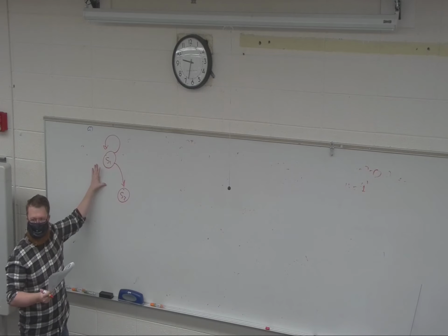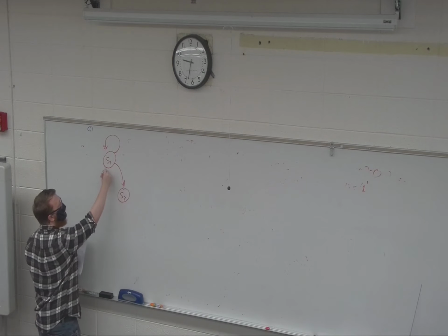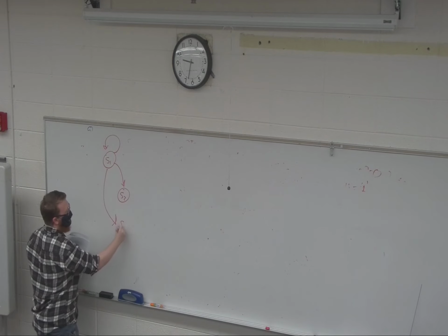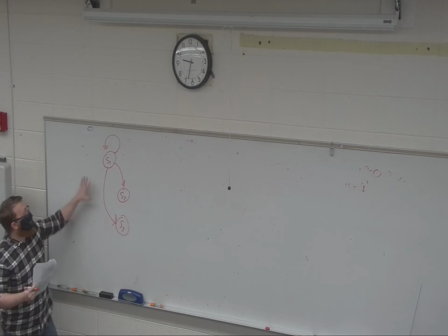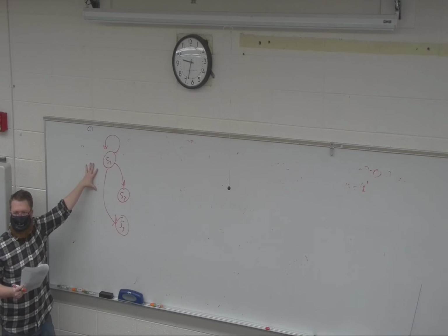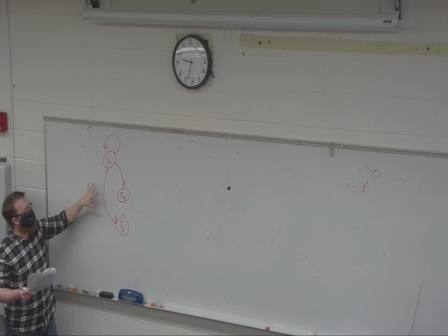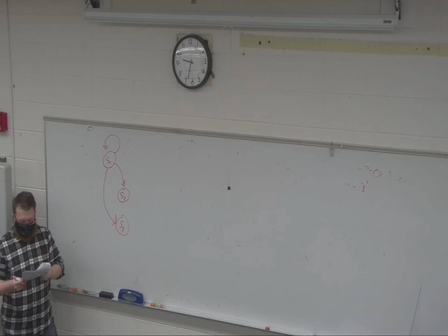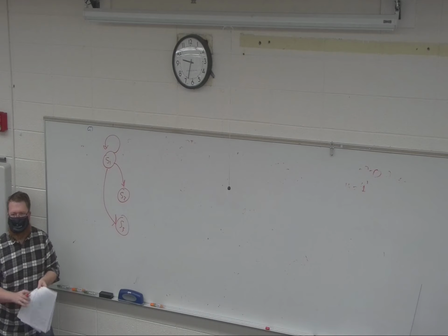I might have other options to step between states, right? I don't have to always go from 1 to 2. And it might go 1 to 3. But once you can start drawing the state machine, it's really easy to start thinking about these state machines as VHDL code.